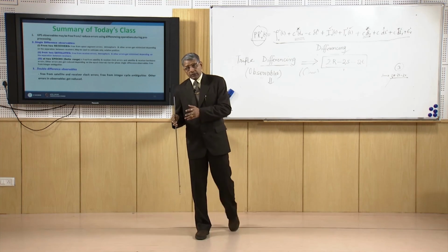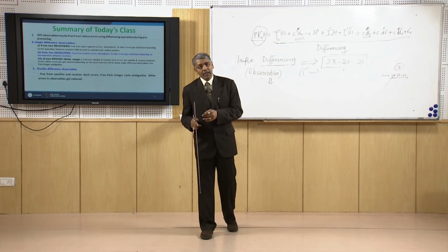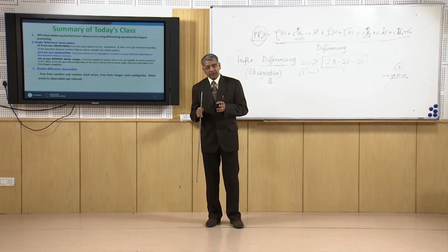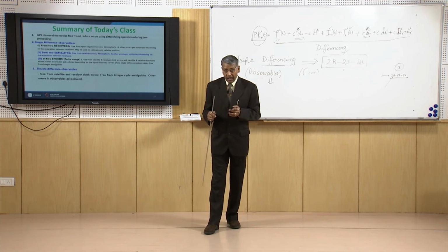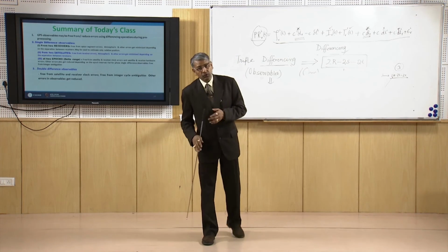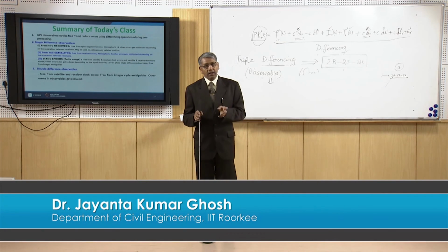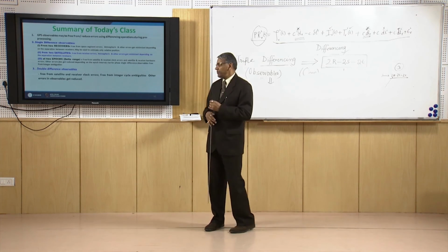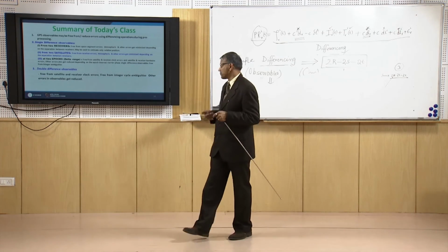However, triple difference observables help us to identify the presence or absence of cycle slip error as well as mistakes or gross errors, and as soon as those are identified through triple difference observables, we can take out those observables, and for the remaining observables we may make use of double difference observables for further processing to find out the GPS position.